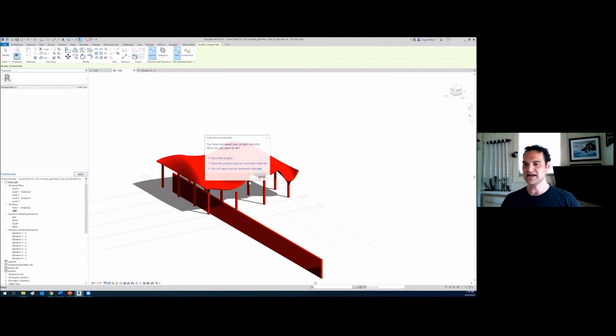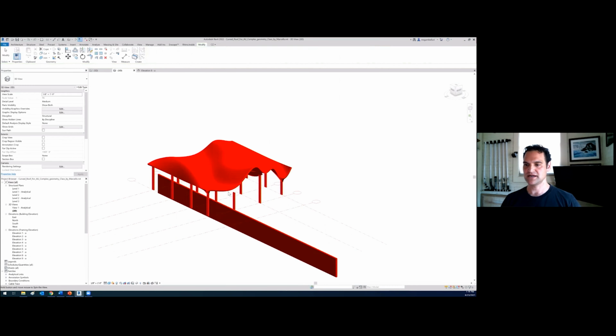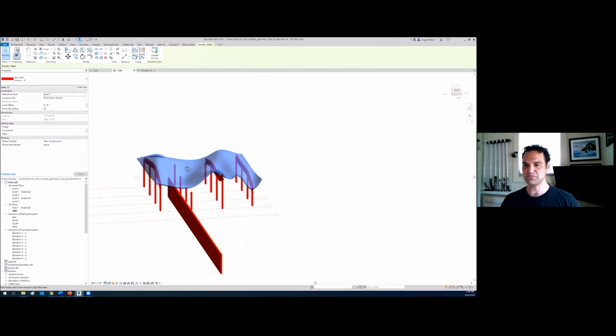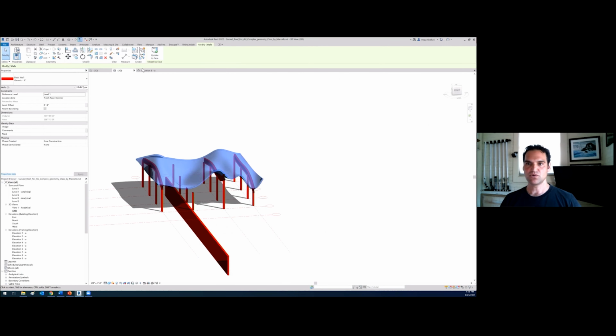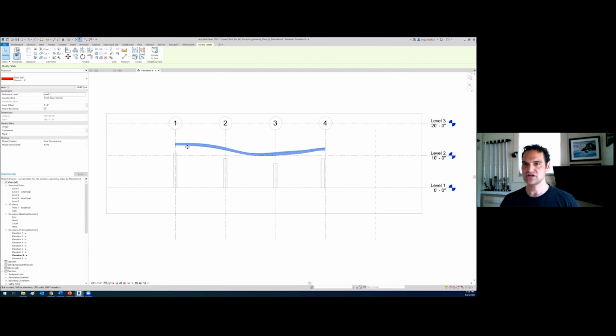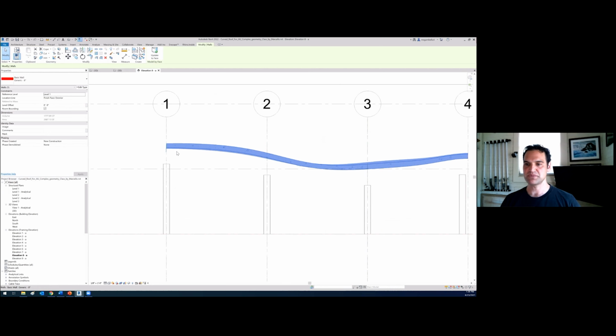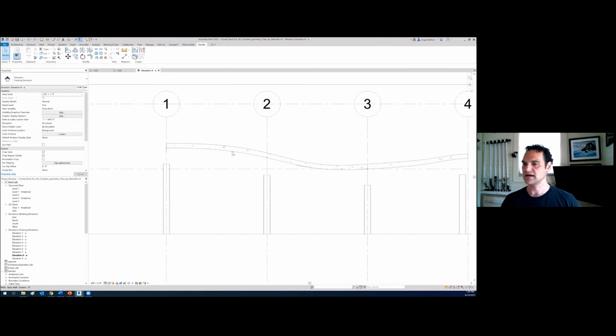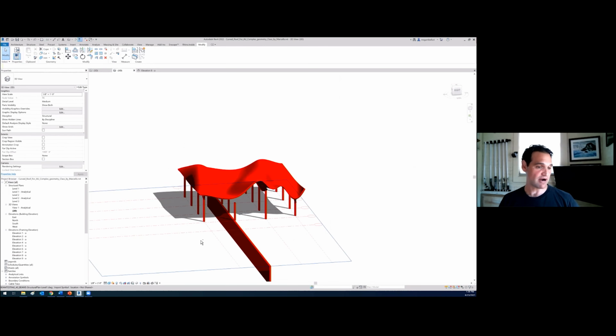Basically you have this canopy right here, okay? Right here, and you want to place a beam along this grid. Well, if you look in elevation, this edge, you're actually not allowed to place a beam and pick the bottom of this, okay? You can only see it in 2D, but you can't pick the bottom. But what you can pick are actually edges.